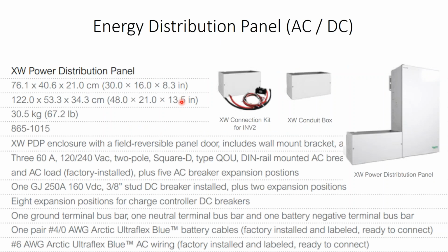All right, so let's look at some of the hardware accessories that go into a battery system. What we're going to start out with is this service panel here. This is a service panel that says, look, we need a DC service panel because we have multiple charge controllers and 2 strings of batteries. And so the 2 strings of batteries need to be wired together. The charge controllers need to be wired together. They need to have a point of interconnection.